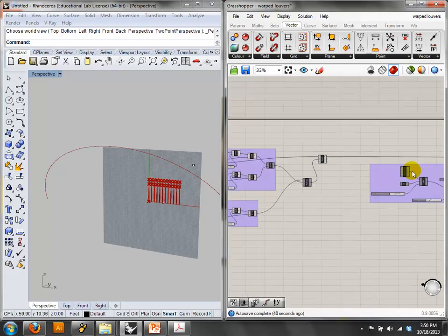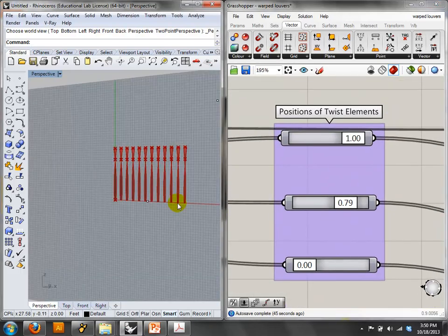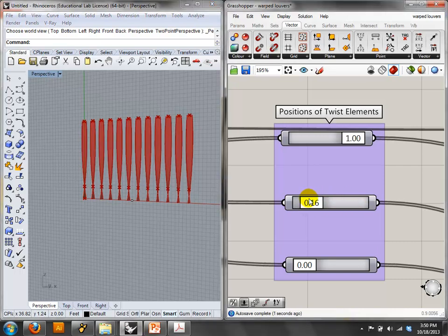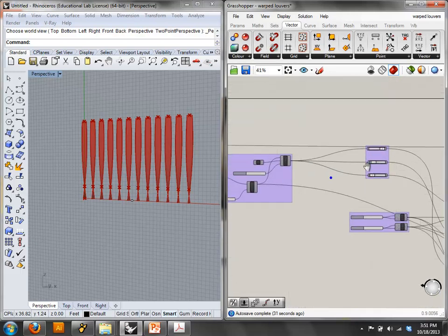And in this script, I have the ability to change the location of that twist element. If I was going to get really fancy, I could parametrically adjust the position of each twist according to some curve or something like that, right? To be really tricky with it. But in this case, they're basically all the same, and there's some kind of mechanical thing that's actually twisting that center frame. And this goes back to the louver pattern that I showed you earlier, where it's just 3 rectangles and then the one in the middle twists. But now, what's twisting the middle one is the angle of the sun. Okay? And there's various ways to do this one as well.